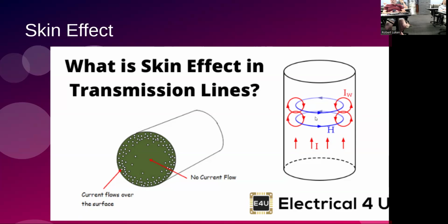And they are actually creating little current loops around them, because as that magnetic field changes, it creates a current orthogonal to it. If you notice the way those rotate, they're reinforcing one another in the middle and on the outside. So it's tending to make the current run closer to the outside of the conductor.